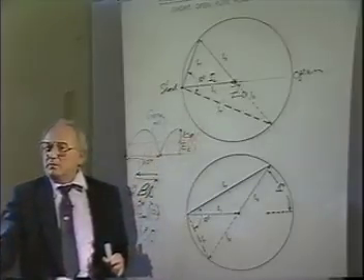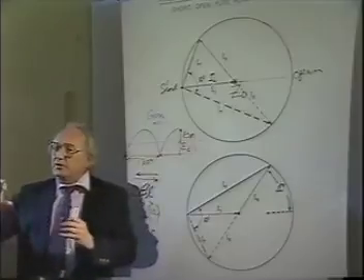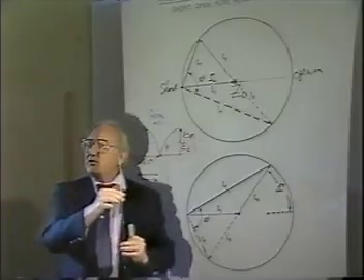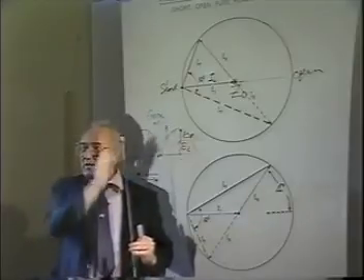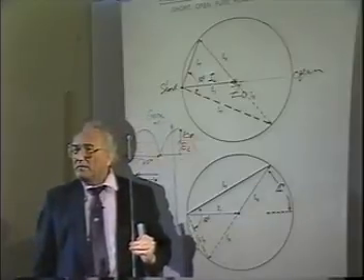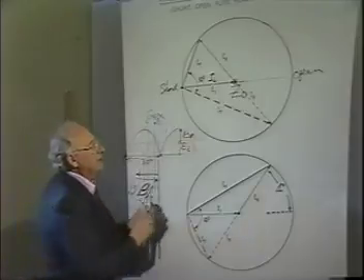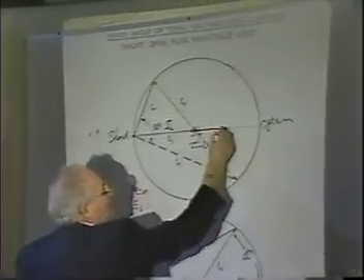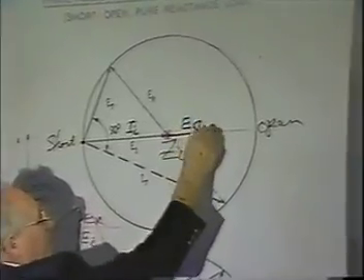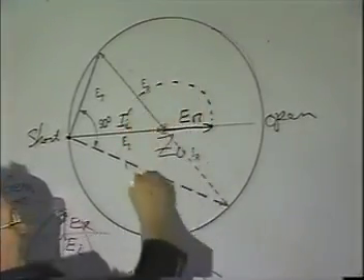Follow this through. When you had a wave traveling down a transmission line and it hit an impedance greater than Z0, what happened? The voltage went up, didn't it? Can you see that's what's happening here? It's going to be the maximum value, isn't it? Because E sub R, if it were only this big, it would now trace out this circle.